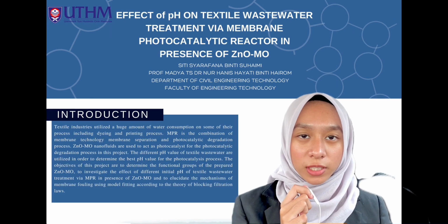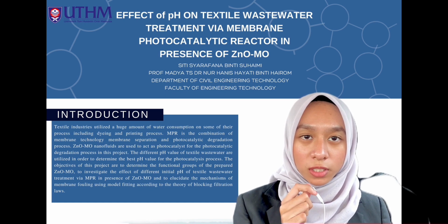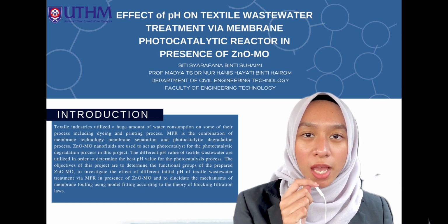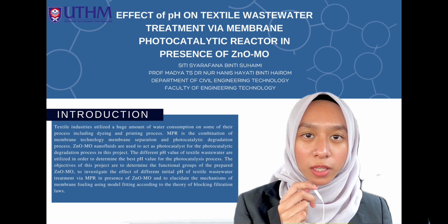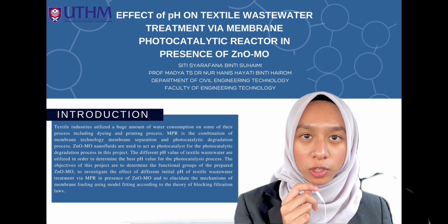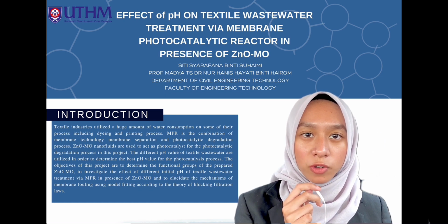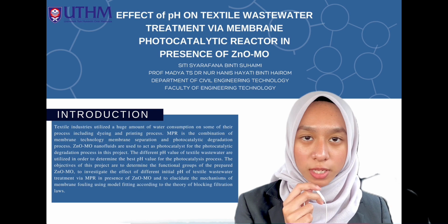As for the introduction, the textile industry utilizes a huge amount of water in some of its processes, including dyeing and printing. MPR is the combination of membrane technology, membrane separation, and photocatalytic degradation process. ZnO-MO is used as the photocatalyst for the photocatalytic degradation process in this project. Different pH values of wastewater are utilized in order to determine the best pH value for the photocatalysis process.